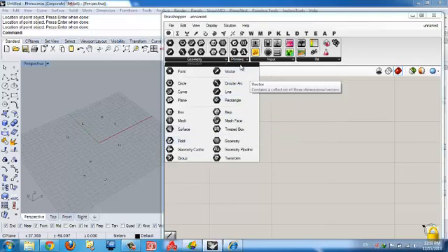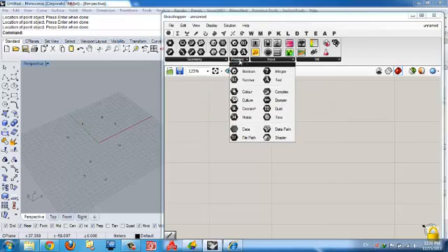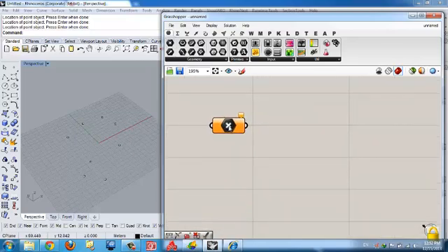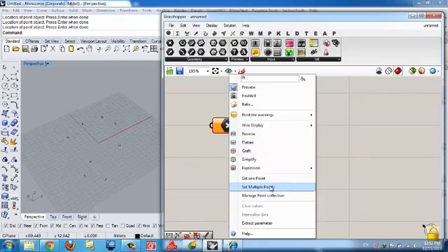And if you have numbers or maybe just not geometrical data, you can move into here. So the first thing I want to do is import these points and interpolate them. So I give a curve, get a curve from them. Okay, I click here and go for the set multiple points.